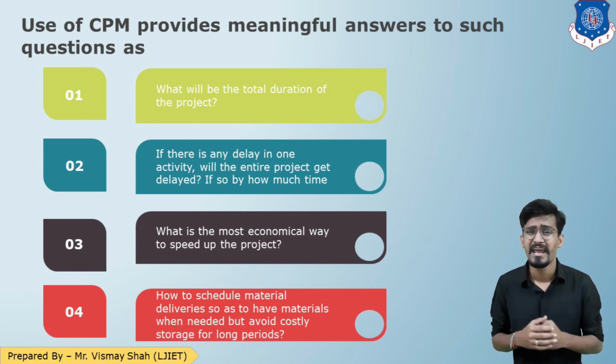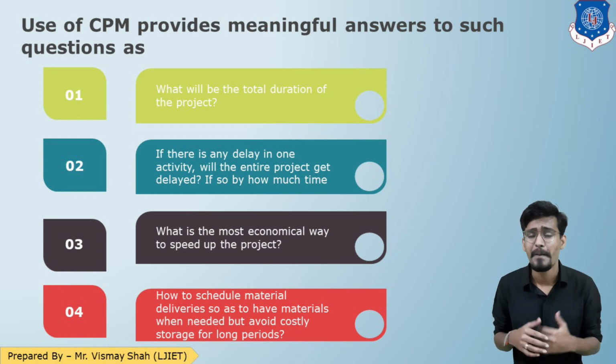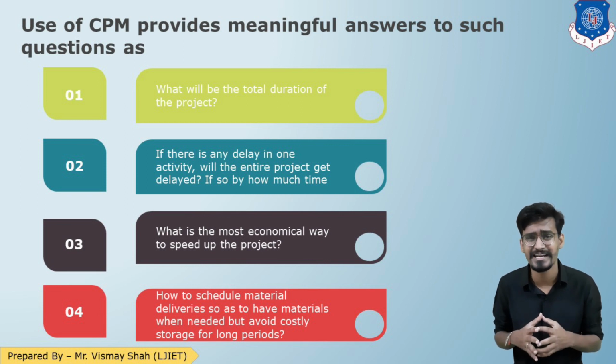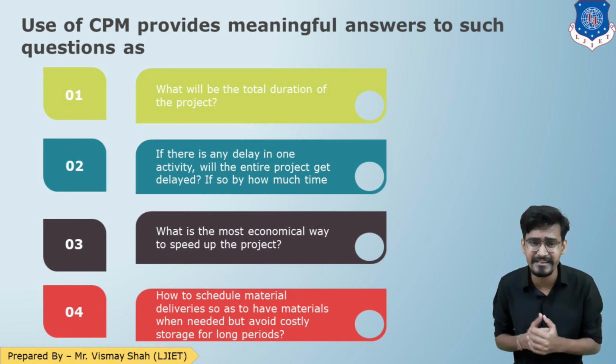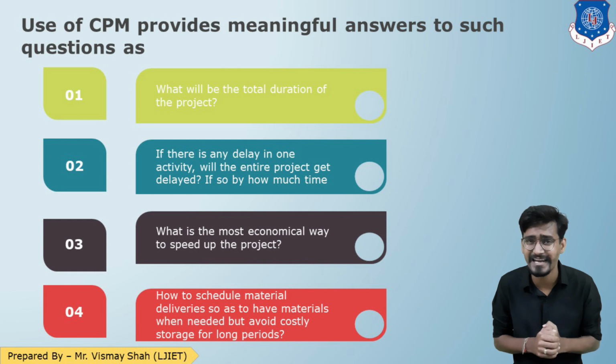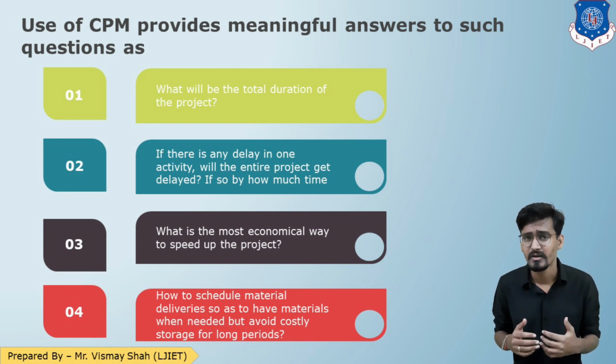Second question is, if there is delay in one activity, will the entire project get delayed? If yes, by how much time? By applying CPM method on a construction project, we can give the answer that if any activity gets delayed in the project, for example, if concrete in foundation work gets delayed, will it affect the project? Will the entire project be delayed? If yes, by how much time? So that can be done by CPM method.